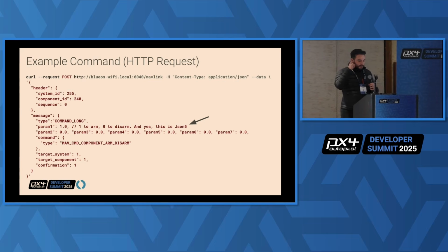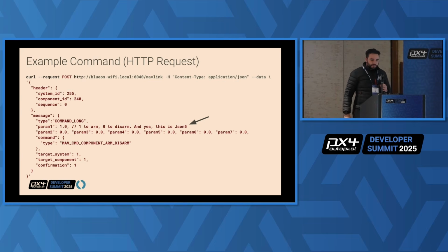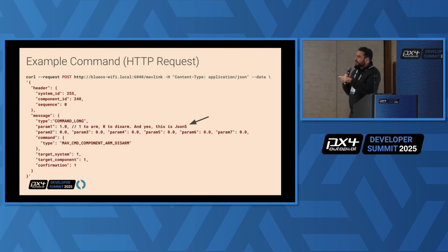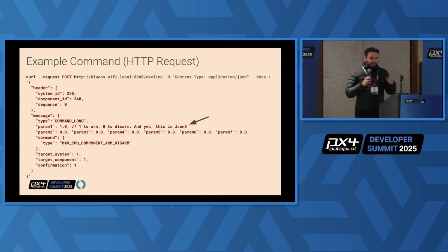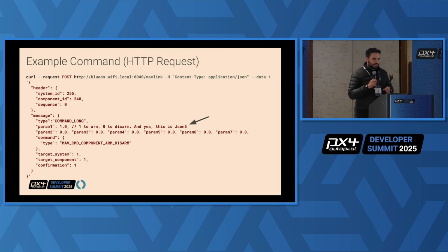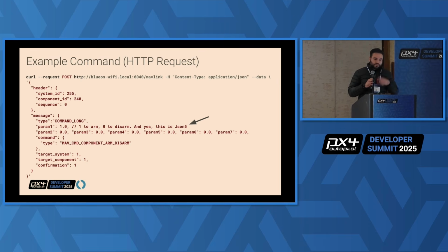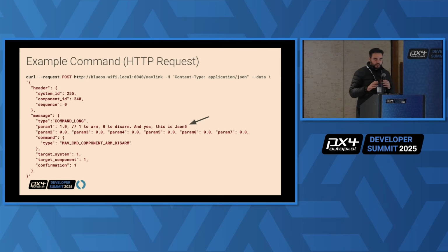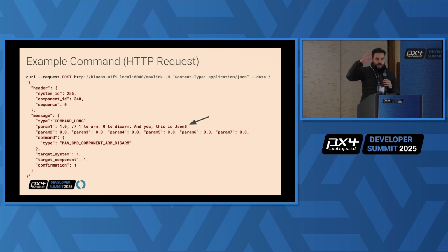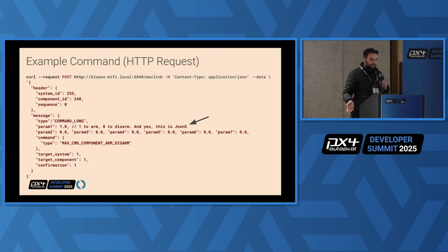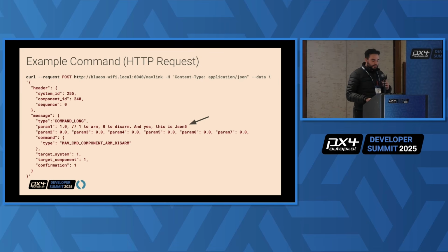And for MAVLink to REST, it's really simple. As I said, you can run it directly on the terminal. And since it's JSON5, you can introduce documentation directly in the JSON. So you can just add comments and do other things, send values as not a number, etc. And you can just do a curl, send the MAVLink payload as JSON, and we're ready to go. Of course, you still need to understand how MAVLink works and how the MAVLink fields operate. And this is possible through the TypeScript definition, where we have the entire documentation.